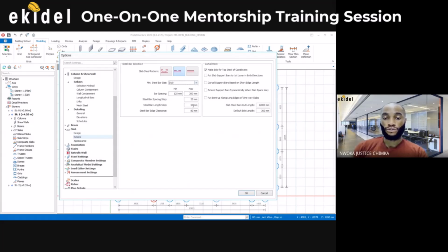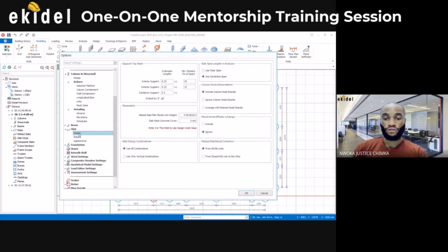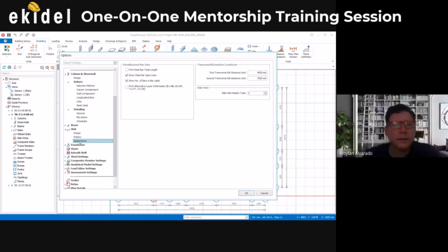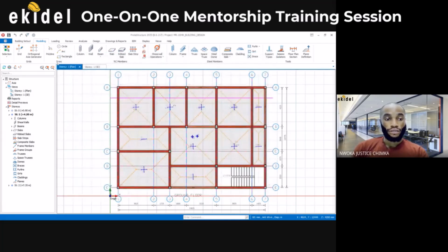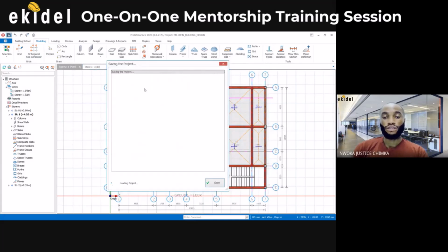So by doing that, also come here to concrete cover. You can see here 25, and that's okay. So that's all the settings. Then now I can just click on print steel bar total length if you want that. Then you can click on save. Then save again. So with that now, we can come to modeling here.